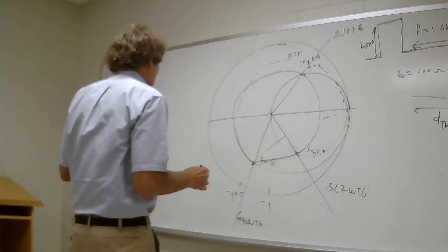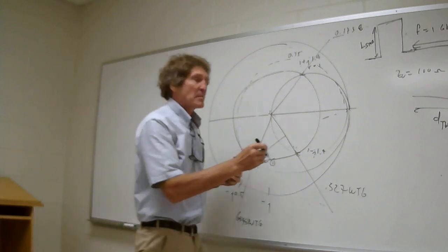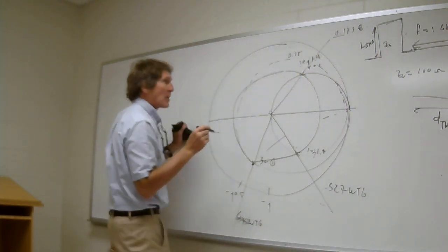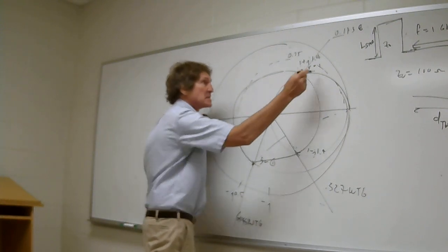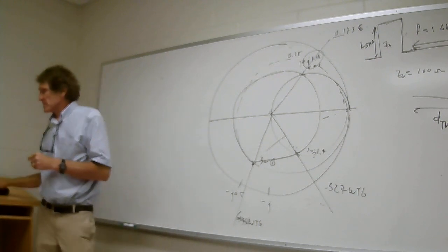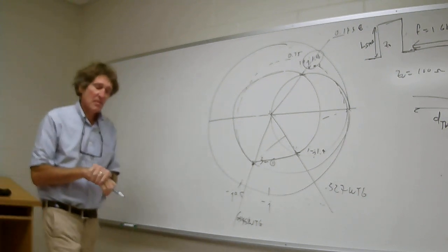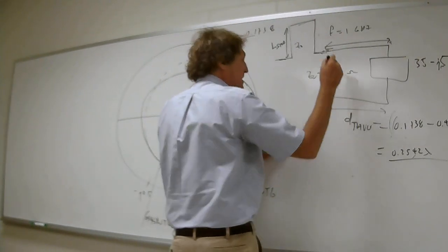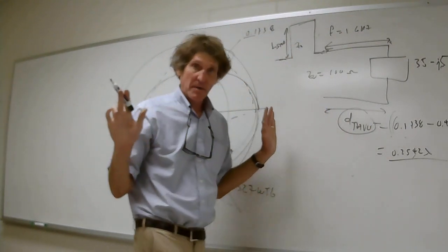Okay. So now, we're assuming the stub has characteristic impedance Z0. Now, I know I want this stub to nullify this, okay? And it's shorted. It's going to be in the impedance domain. Please just take a moment, get this down. I want you to watch what I'm doing and why I'm doing it. This is going to be with a short circuit stub, so only the length of the top is the transmission line. Everything else is just a wire. The length from here to here is d. It will be the same.